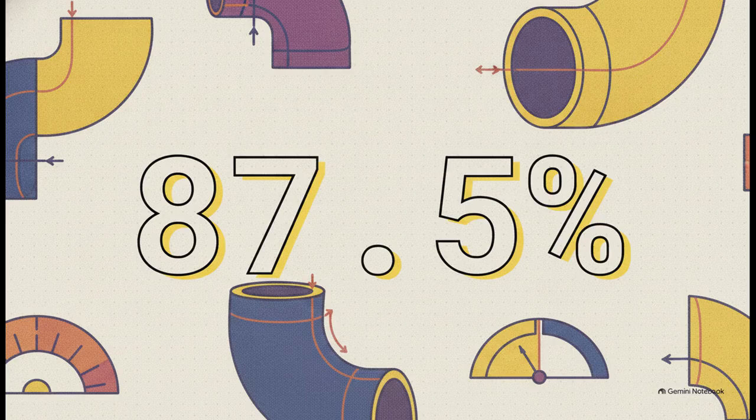So, the crucial point here is this hard and fast rule. The wall thickness of the fitting must never drop below 87.5% of the nominal thickness marked on it. Why? Because forming a short radius elbow physically stretches the outer curve and compresses the inner curve, making it incredibly difficult to maintain thickness. In fact, in those localized bent areas, the standard dictates that the metal often must be even thicker just to ensure it safely matches the pressure rating of a straight, seamless pipe.